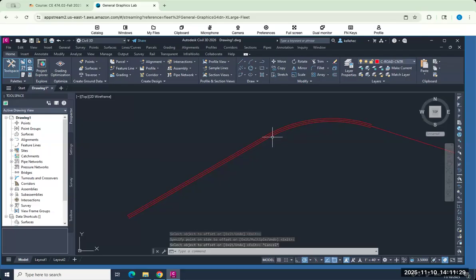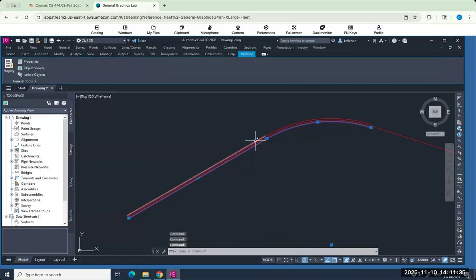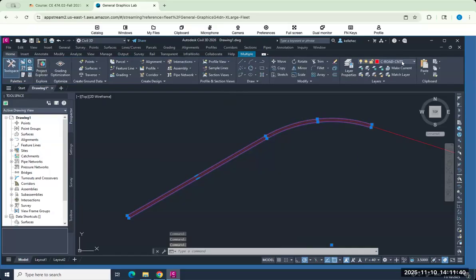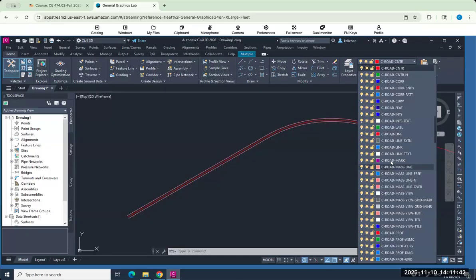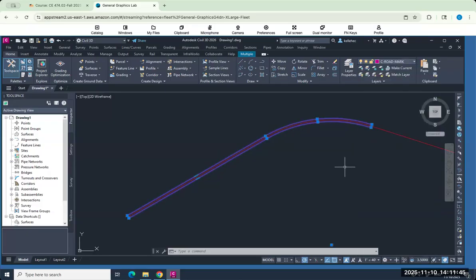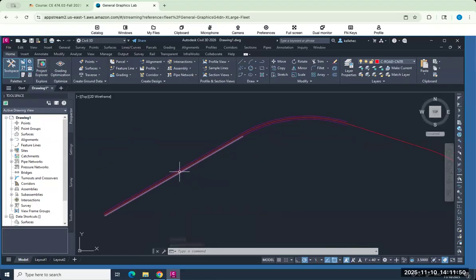You are going to want to use different layers for different parts of your road. So in this case, I can select these different lines, and if I want to move them to a new layer, remember, you can go up here and just by selecting them and clicking a new layer, you can move them to that new layer. So we have our center lines, we have a cartway, we'll add a right of way, and I actually today will tell you to add a curb. So I have information on what those criteria are. Again, you're primarily using offset to do this.